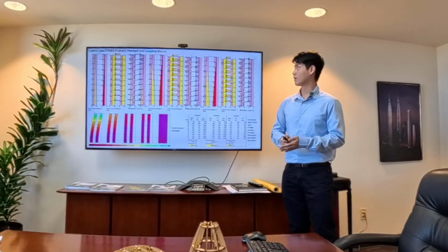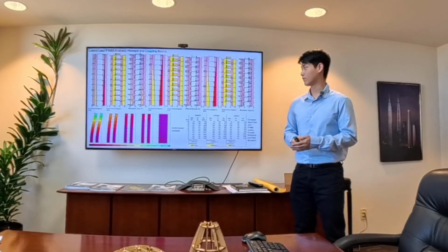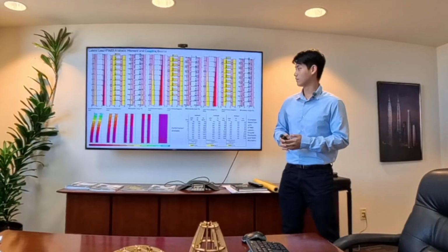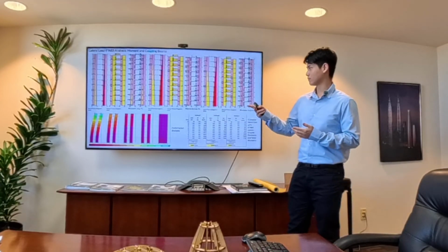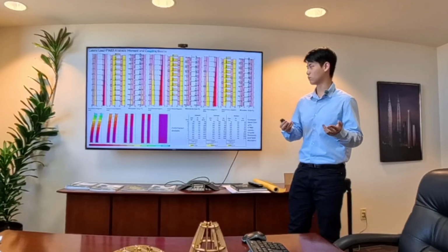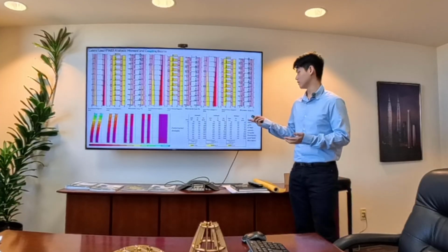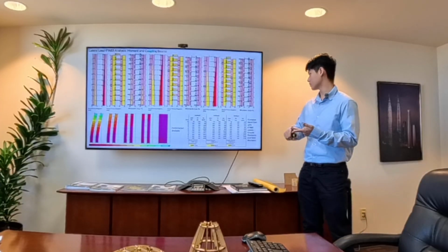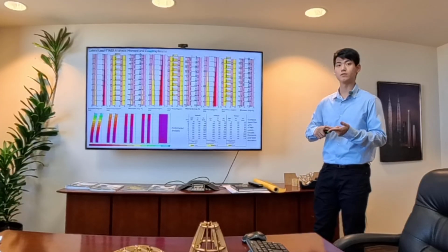This was a lateral load ETABS analysis Mr. Shim provided me to study moment and coupling beams. I observed the axial forces, shear forces, and moments, and I also calculated the moments and coupling moments by hand, compared them with ETABS, and observed the differences that occur.